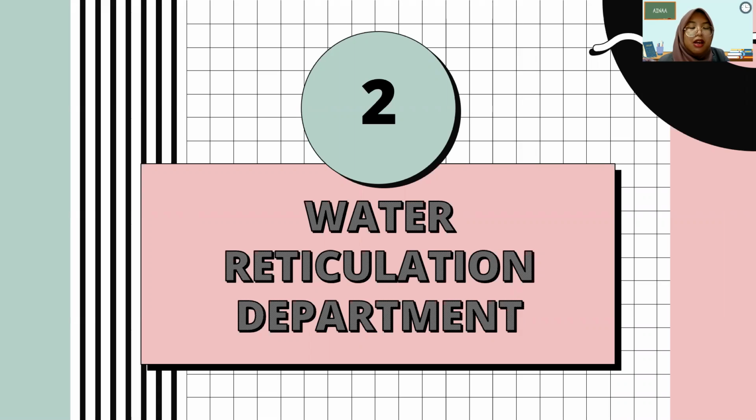Basically, water reticulation is a water distribution network that collects and treats water before distributing it to consumers. An adequate and sufficient supply of water is essential for cattle to drink, feed preparation, and for sundry other uses. The factors that need to be considered for implementation of a water reticulation system include size and types of pipe, location of pipe, design of flow rate and pressure, location of storage water tank, pumps, and so on.